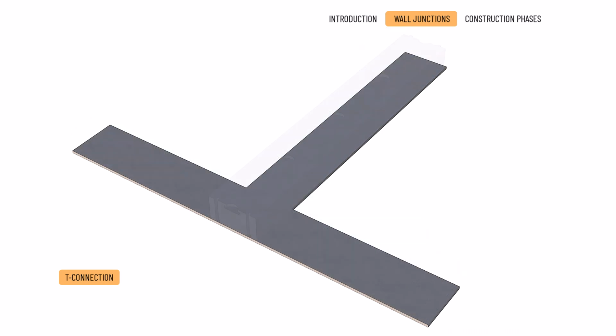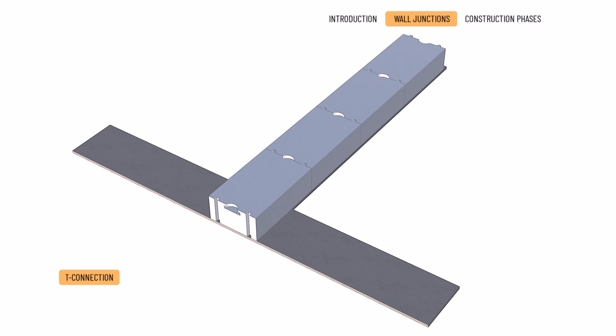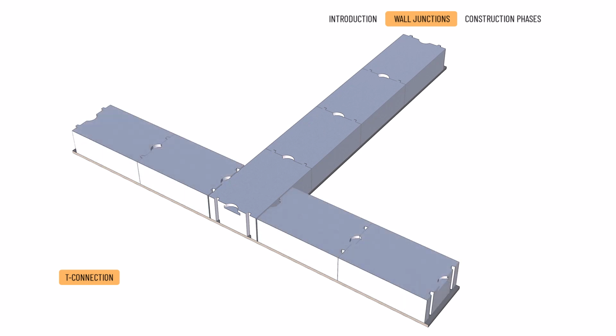We bond the adjoining wall to the main wall already in the first course, placing a whole block. Because of the wall width of 37.5 centimeters, the piece of 60 centimeters length will overhang the main wall with 22.5 centimeters. This will be the overlap size in this wall section too.